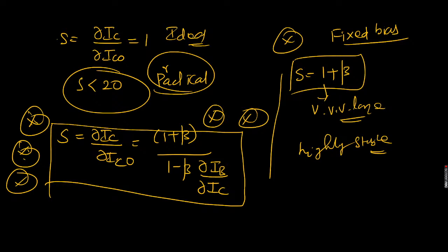Apart from that, next we use the transistor to calculate the voltage gain, current gain, output voltage, and input impedance, that is when the BJT is acting as an amplifier. We saw 4 regions of the BJT in total: active region, reverse active region, saturation region, cutoff region. But in which region is our transistor most preferably operated? Only in the active region, because only in the active region can the transistor act as an amplifier.